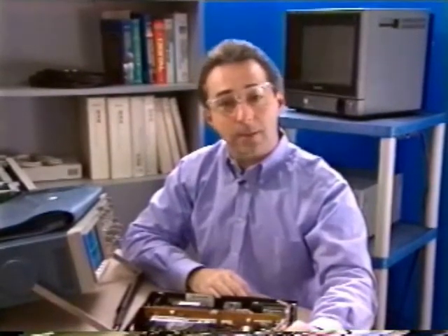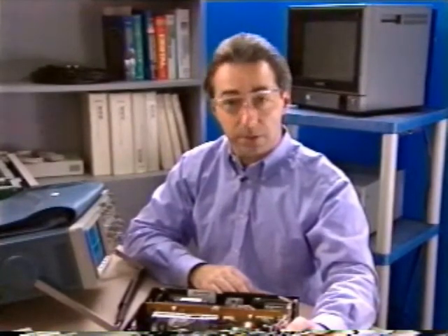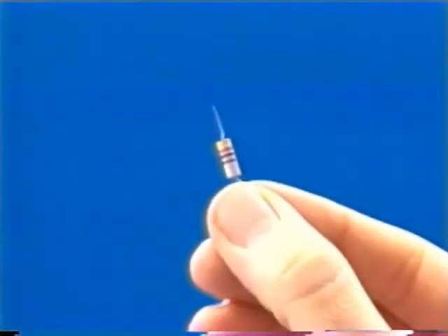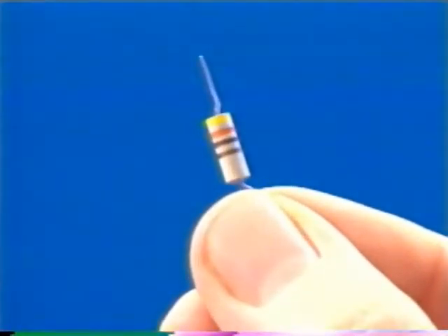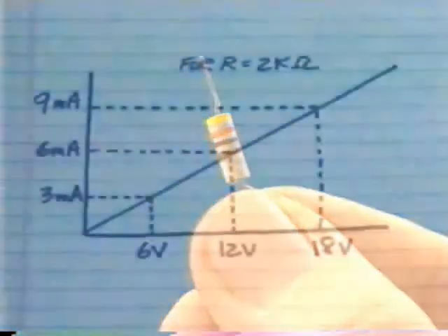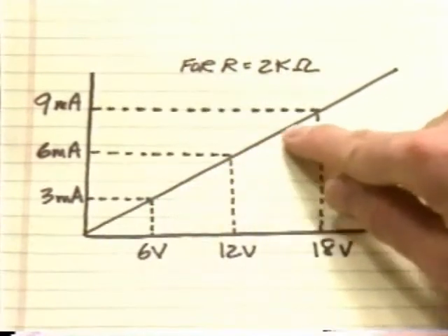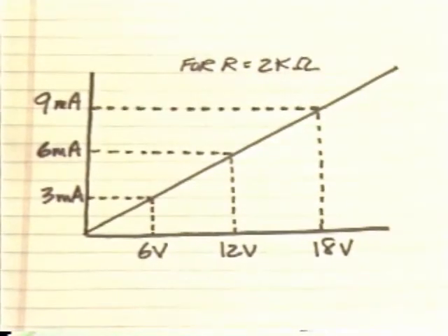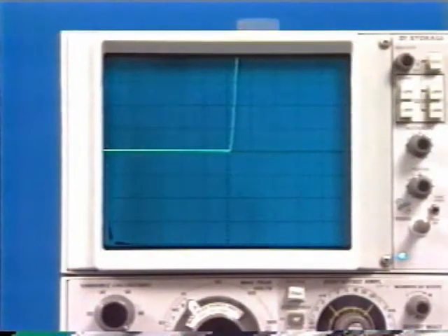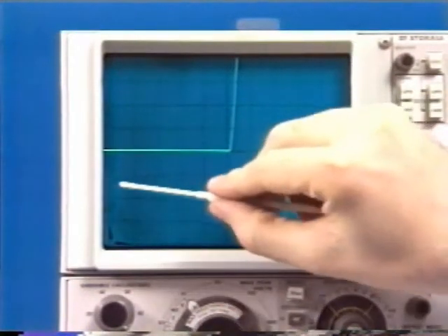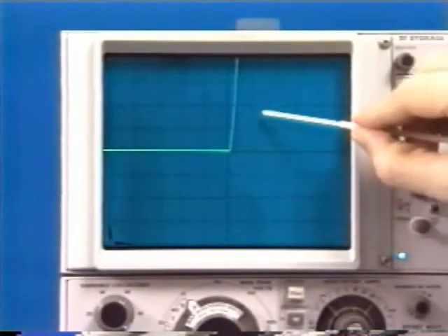As you study semiconductors, you'll often hear the junction diode referred to as a nonlinear device. This means that the changes in current are not proportional to the changes in voltage. The opposite of nonlinear is linear. A resistor in which changes in current occur in direct proportion to changes in voltage is known as a linear device. If each pair of corresponding current and voltage values for a sample resistor are plotted, they will form a straight line. This is why a resistor is called a linear device. But the volt-ampere relationship of any nonlinear device, such as a junction diode, will always form a curve.